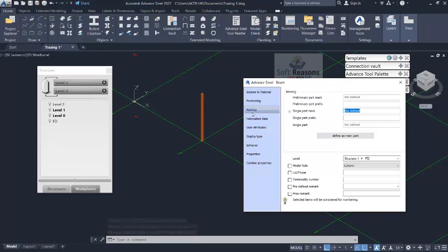But if I come to this naming provisions, you see here, I'm having foundation right there. So you can now click in these provisions and set it right, which is the top constraint. The bottom constraint is level 0. You can set it right there successfully. The model row is column. Click on close right there.